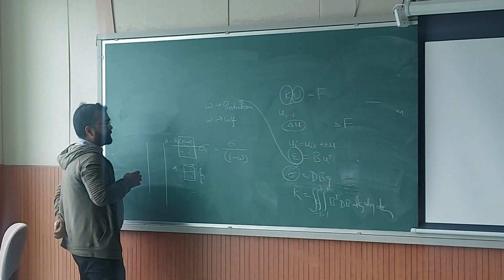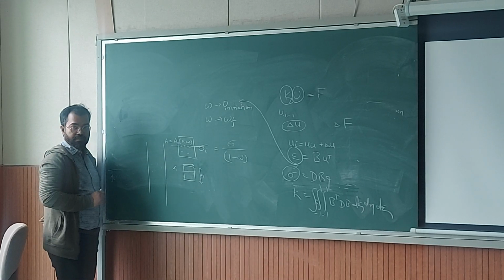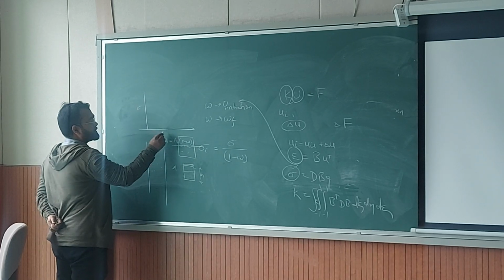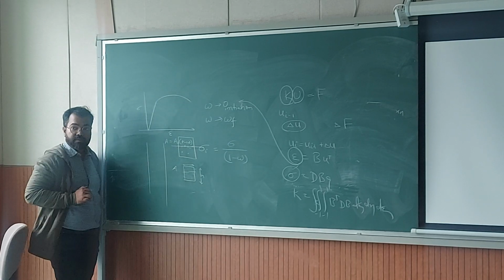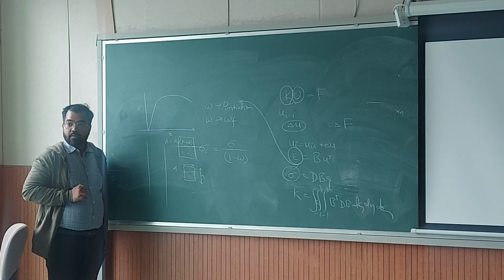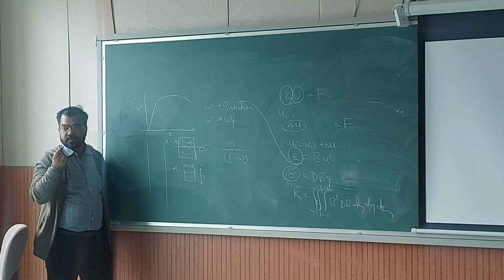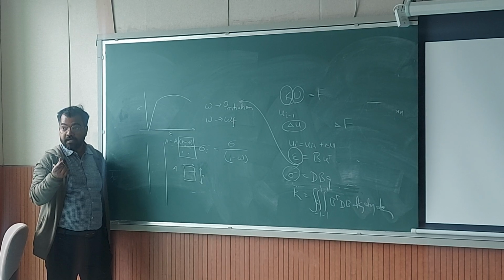So if you model a tensile specimen using this formulation, then only you can simulate the real stress strain curve, whatever is the shape of this. Okay, even though true stress should be going up always, but the reality is that the sample will neck, right?